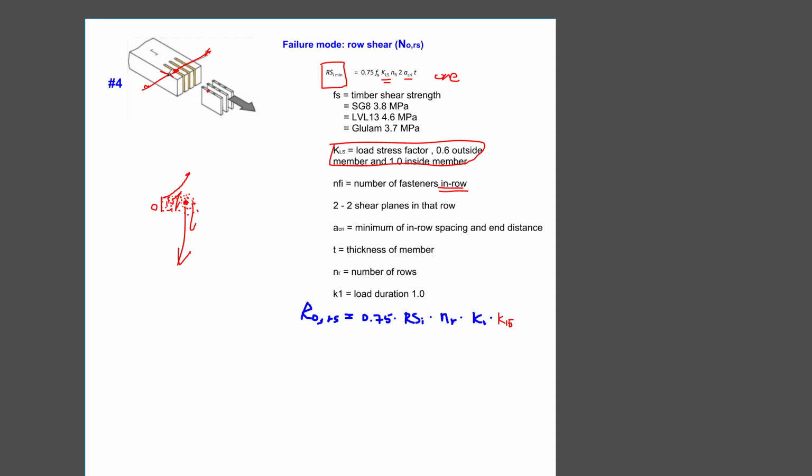So if we draw this stress profile along this line from edge to edge, okay? And if there is one dowel, two dowels, and three dowels, then your stress profile would essentially look like this, right? Particularly at the end region here, you can say our stress is increasing from zero. And if you take the average of that, it's going to be 0.5 basically, something like that.